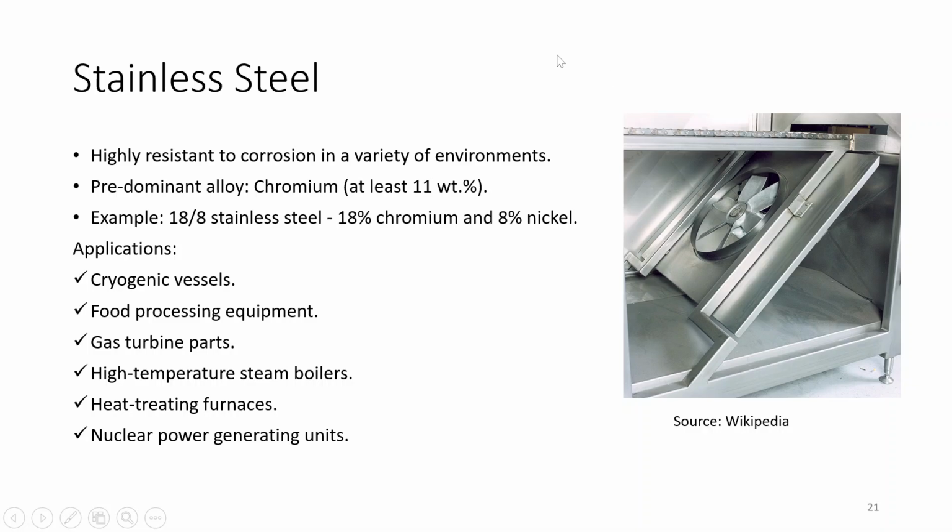Pig iron already has a lot of carbon, up to 4 weight percent. So you try to dilute that carbon percent. You basically add oxygen to it so that CO2 forms, and the carbon goes outside of the steel. So you already have the carbon percent, and you have to bring it to the required percentage. You don't basically add carbon to it, but you can add it as well if you have pure iron in that case. Okay, ma'am. Okay.